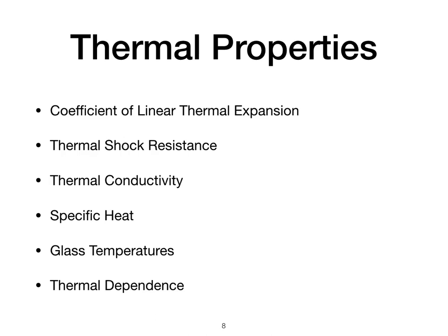Melting point is the temperature at which the raw materials melt to a liquid state. Working point is the temperature at which the glass melt is shaped or molded. Softening dilatometric point is the temperature at which the glass begins to deform during heating when measured in a dilatometer.